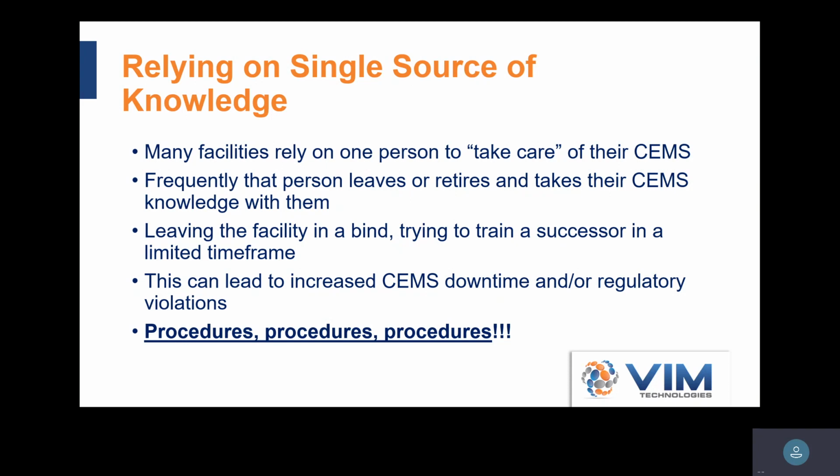So I think the key here is to have that person or persons write procedures on what they do and how they do it, and then show the other newer technicians how to do the procedures and why they're required. You can include all these procedures, like I said before, in your QAQC plan. They're required to be in there, so you can make that plan a real useful tool. But again, I can't emphasize enough to have procedures for maintenance, for QA tests, for what's the response if the CEMS is malfunctioning. Those are all requirements, and frequently those procedures don't exist. So if your old timer leaves and takes all that knowledge with them, it could be a real bind.